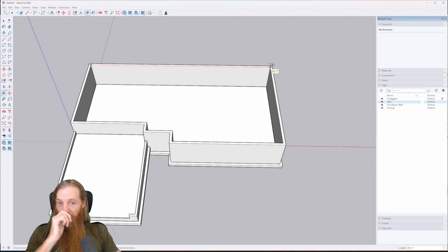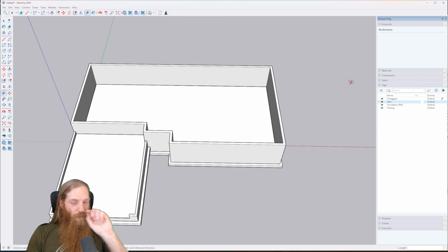So this is like 60 foot. So you're going to have 2 overlaps in the middle of this wall, right? It's basically divided into thirds. So you'll just add another couple feet for each overlap there. I usually do that while I'm adding everything up, and I find that's easier than taking the time to actually model out all the individual pieces of rebar.